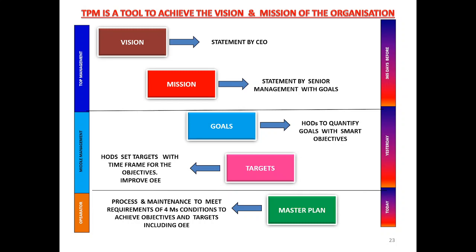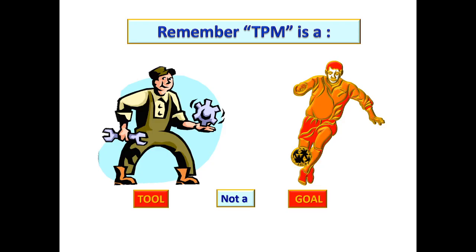The fourth M is materials. Ensure the quality of raw materials and consumables meet the required specification. Also ensure whether there are defects and shortages. Are they stored appropriately for easy inventory control, and also ensure the first in first out procedure is followed strictly. These are some of the important points against 4M which shift personnel should understand fully and follow. Understand that TPM is a powerful tool and not a goal.